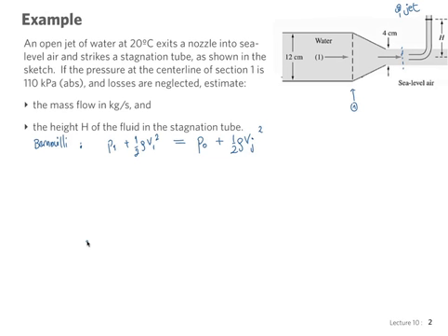Okay, we don't have any of those velocities, but we do have pressure. There, we have the pressure at section 1, and P0 is just atmospheric pressure. And so let's rearrange this a little bit and write P1 minus P0. Of course, here we are assuming incompressible ideal flow, and we are assuming Z1 equals Z jet, and of course P0 is atmospheric.